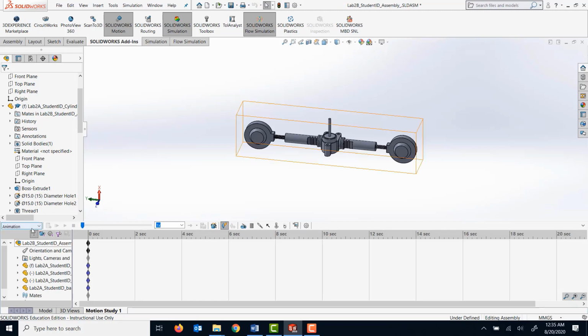And in here, in the first lab, what we did, we only used the animation, which basically was not solving the true motion or equation of motions. It was just creating the animation. If you click on this box, you will see there is basic motion, and there is motion analysis.